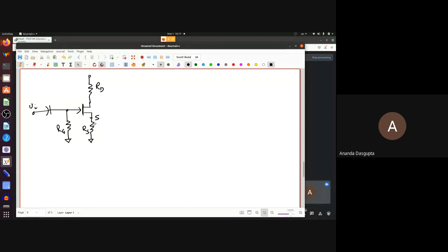VGS, I'm talking about the DC part here, VGS is minus IDRs. So you have this sloping straight line instead of the vertical straight line of VGS being constant in the biasing circuit, which makes the fluctuations smaller. And then you take the output across this. And of course, what makes fluctuations smaller also reduces the gain.